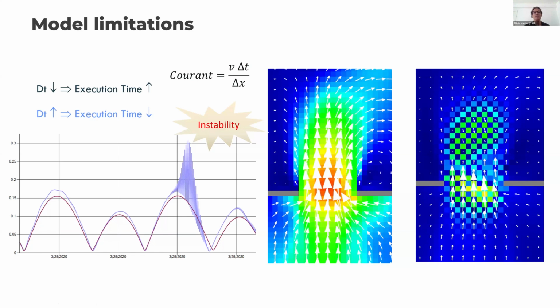So if you increase the Courant number too much, your model gets unstable. Usually, the explicit models cannot have Courant numbers higher than 1. The limit is 1. In ADI models, in this alternate direction implicit, our experience is that it depends on the system, the bathymetry, the forcing, lots of things, but we can aim at reaching 8 or sometimes 10, okay? It means it's 10 times faster than an explicit model. But even though we have this limitation, okay?